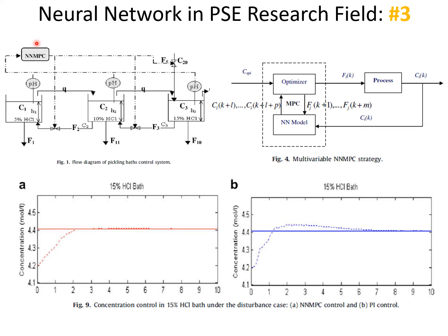The neural network MPC. So for the MPC optimizer we use model predictive control, but the model is based on a neural network model. So the same strategy as before, but not as an inverse model as a controller, but as a model itself. Again, using the normal inputs, the various past inputs, past outputs, and so on, and the neural network comes out with a prediction with a range of outputs.